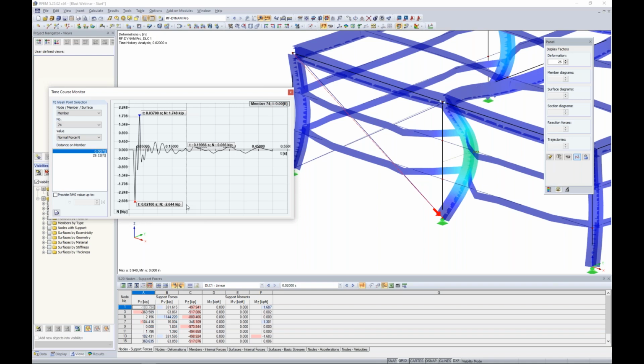So why is this? Well, this is just simply a limitation of the linear solvers. Any non-linear element, so when we're talking tension-only members, they are going to be automatically converted into truss elements for the linear analysis. So the program only knows what it knows, and if it sees a truss element internally, it's going to think, okay, well, then it can take on these high compression loads as well. There's nothing stopping it. Same thing with nonlinear supports. So if we have supports that are failing in uplift, sure, that's easy enough to define in RFEM for the static analysis, but this linear solver will convert it to a linear support when it runs the dynamic analysis. And finally, something like nonlinear materials. So plastic materials for steel design will be converted back to linear elastic materials.